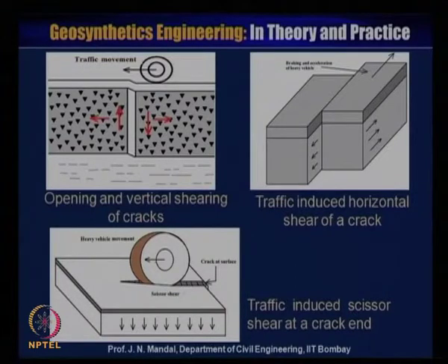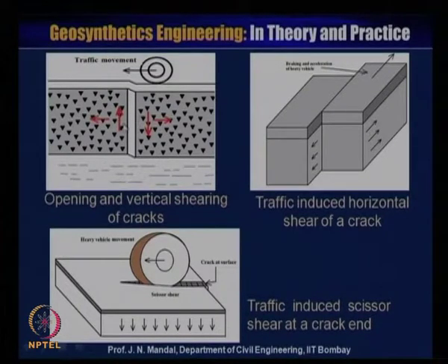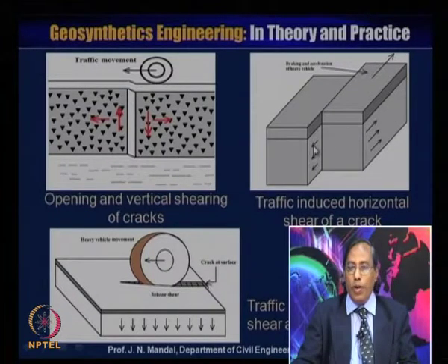Also, you can see opening and vertical shearing of a crack. When the traffic moves, it goes down, it goes up, so there is a formation of shear and it opens, so the crack also forms. Also, there is traffic induced horizontal shear of a crack, and this is due to braking and acceleration of a heavy vehicle.